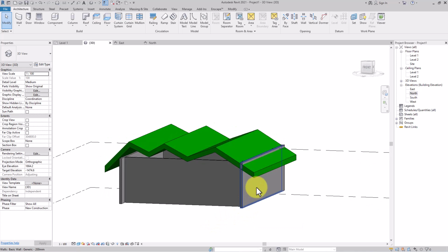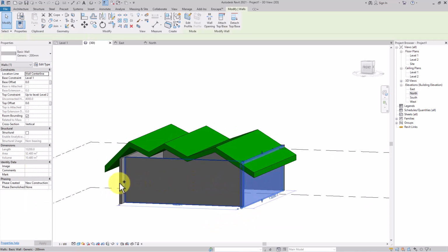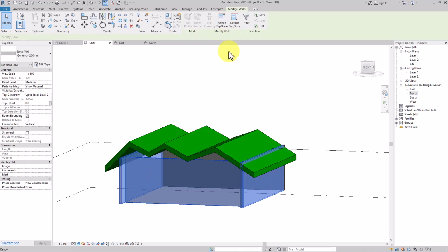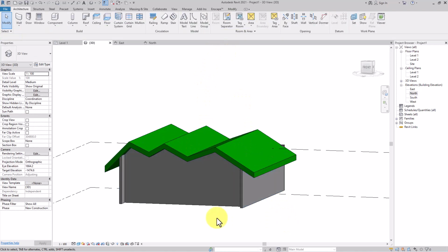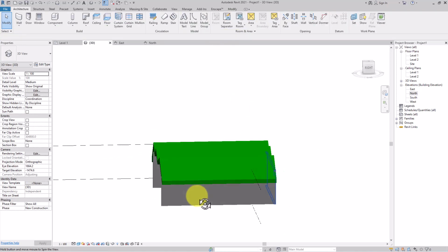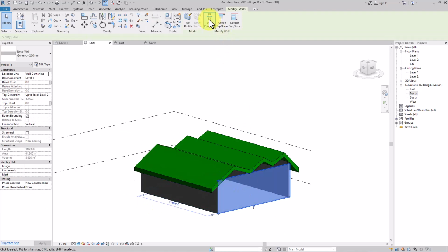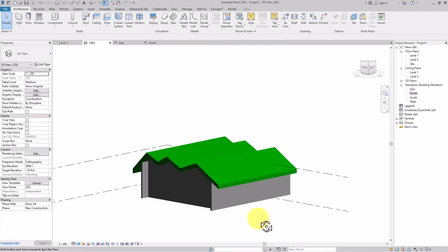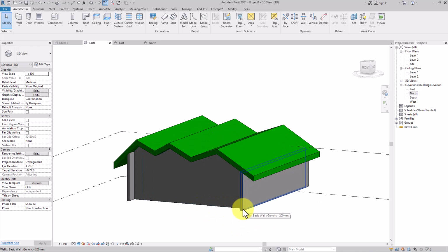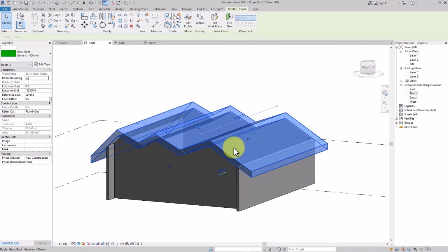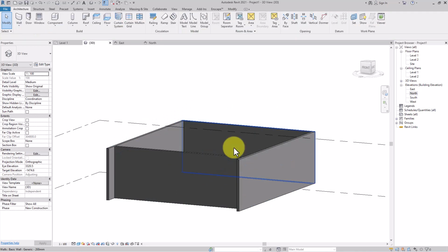Look at this. Same, you will select the walls, multiple walls with the control key, attach top base, click here, and that's it. All right, same thing you can do as well. Click here, attach top base, and click here. Wow, very nice. Look at this, amazing, right? Same, if you have any curve roof, you can design. If you delete, it will make flat walls as well.